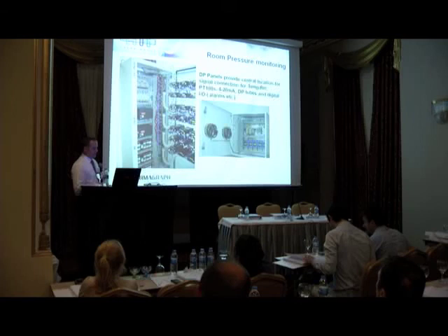Everybody likes the trends, but actually the real thing that matters to you is your alarms. So when you produce something, you can very simply select the time base of when you produce the product over, and you can produce a reconciled alarm report. And this can generate all sorts of fancy things, but basically you look at a specific time period, and you might want to look at all alarms per alarm zone. Now, an alarm zone, if you've got a big system, might be a particular production area, or it could just be a particular room, or it could just be an isolator.